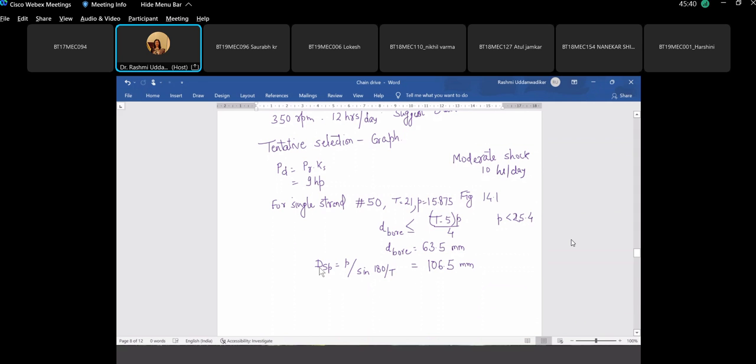Okay, so knowing this diameter, knowing the RPM, let's find out what is the peripheral velocity first. Pi into this diameter into N1, it is rotating at 1000 RPM motor. What is the peripheral velocity? And if T1 is 21, what is T2? Is that 5.57? Yes.